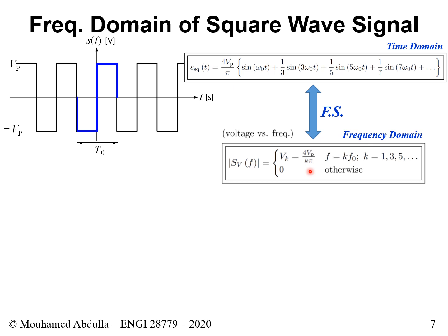You find the peak, which is this. You move from the peak to the RMS value, so you basically take this and divide by the square root of 2. Once you have the RMS value, you use Watt's law to find the average power. So that's the third step. Once you have the average power, you do 10 log 10 of the value that you got, and that gives you the result in dBW. Once you have the value in dBW, you add 30 to it, and the result will be in dBm. So there are 5 steps to move from a peak value to dBm.